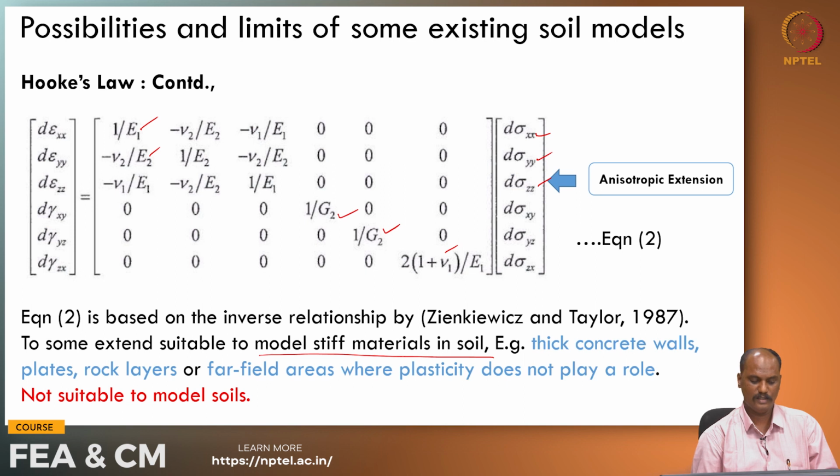So, in these conditions we can pick up Hooke's law for modeling the material. And as a caution, I would say that it is not suitable to model soils. This is a very important point. What I would like to say is, we can consider this relationship where plasticity does not even play a role. Okay.